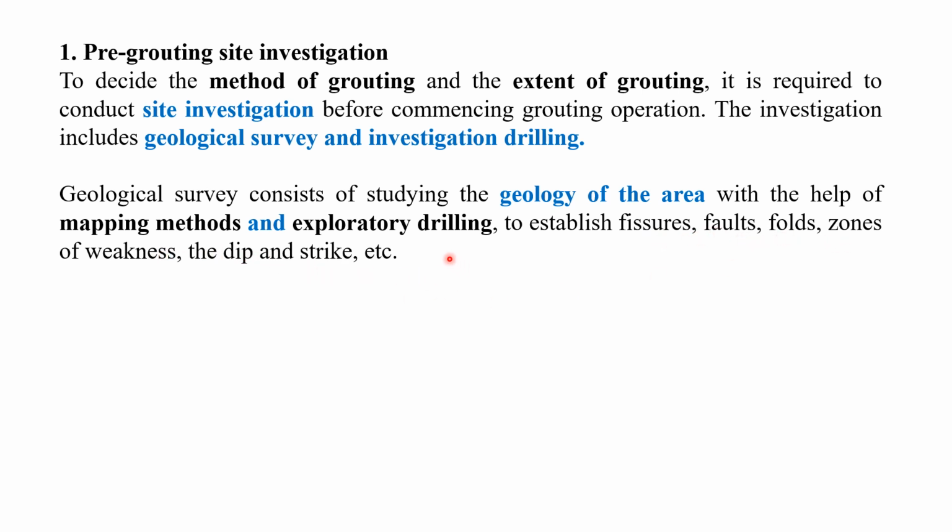So we have to know whether the fissures, faults, folds, and zones of weakness are available at our site. That means we have to know the location of the groutings, where we have to go for the grouting. We have to know the type of soil, the type of fissures, faults, folds. Geological study we have to carry out first.